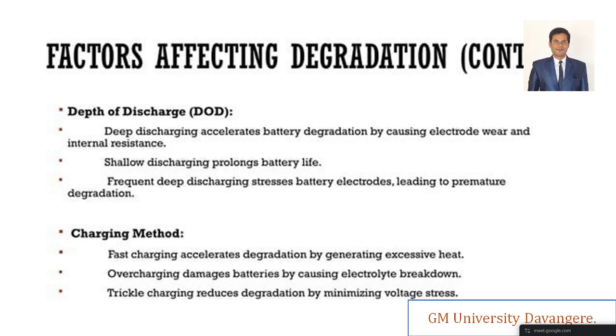And also when you talk about overcharging, right? For example, you charge to 100%, and you do not unplug. You stay plugged in for a long time, right? So what will happen? Again, it will get overcharged, right? For example, if the cell is at 4.2 volts, and it is charged to more than 4.2 volts, what will happen to the cells? It causes the electrolyte to break down. Yes or not?